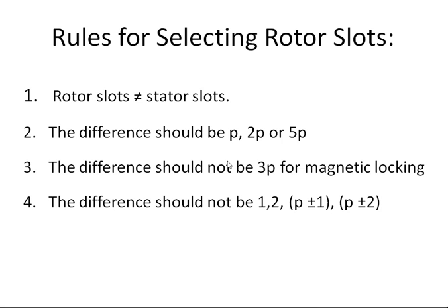Similarly, we know that if the number of stator slots and rotor slots are not taken into proper consideration, then a large amount of noise will be created because of the tooth pulsation. Losses being developed will be larger. So the air will have larger obstruction, and that obstruction will lead to a large amount of noise. So vibration will also be produced due to this noise. So there are certain rules which have been laid down so that the rotor slots can be effectively chosen.